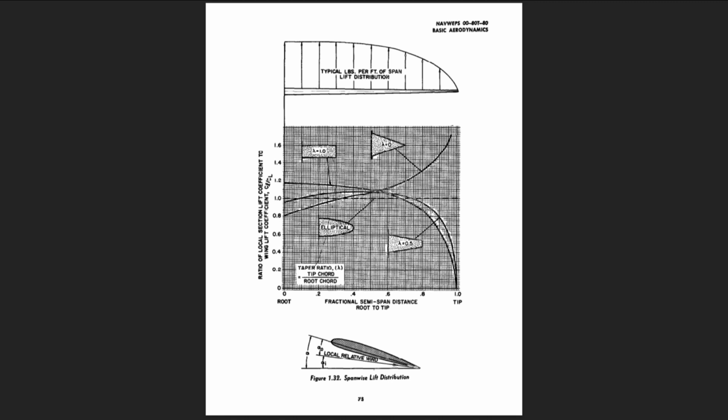In the aerodynamic sense, the elliptical wing is the most efficient planform because the uniformity of lift coefficient and downwash incurs the least induced drag for a given aspect ratio. The merit of any wing planform is then measured by the closeness with which the distribution of lift coefficient and downwash approach that of the elliptical planform.